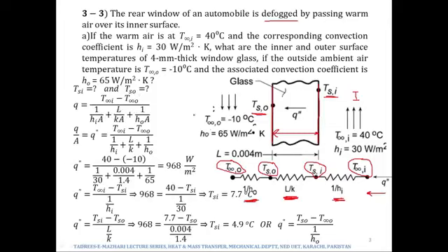As just described, since we are not given the area, we will take the area common out of the denominator, which will go into the numerator, and it will get multiplied with delta T. And from here we will take the area into the denominator of the left hand side of the equation, and we will call this Q by A as heat flux.